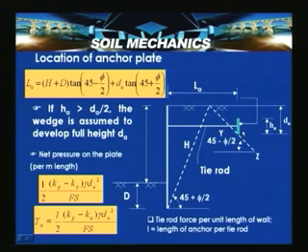Now, the net pressure on the plate, this particular plate per meter length, is given as follows. We know that this is passive and this is active, so this is the active diagram and this is the passive diagram. When you compute and apply a factor of safety, and dA is the depth. Because we assumed that HA is greater than dA by 2, the entire full wedge is participating. So, it is (Kp minus Ka) into gamma dA squared by a factor of safety, which is shown here.